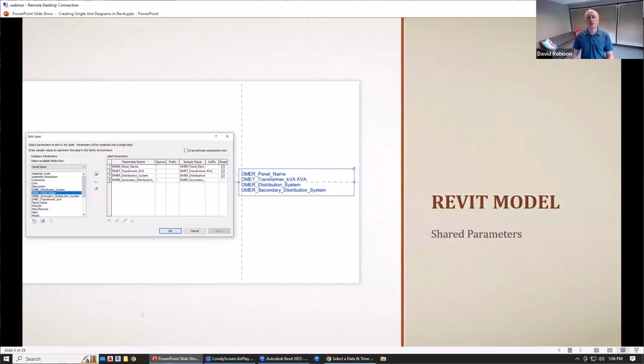The other Revit feature I want to highlight are shared parameters. This is information you can put in your family, either to drive the geometry or to store information about that family. And then you can use these shared parameters to do all of the scheduling that Revit allows you to do. So your families are going to be holding all of these shared parameters, and you want to be comfortable creating these, again, modifying them, inspecting them, and then using them for your schedules and for your annotations.